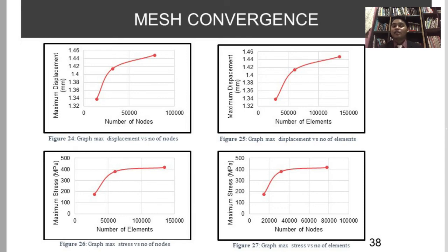So we can see that it's almost constant. Even if it's not fully constant, it's almost constant. So our mesh convergence is complete.